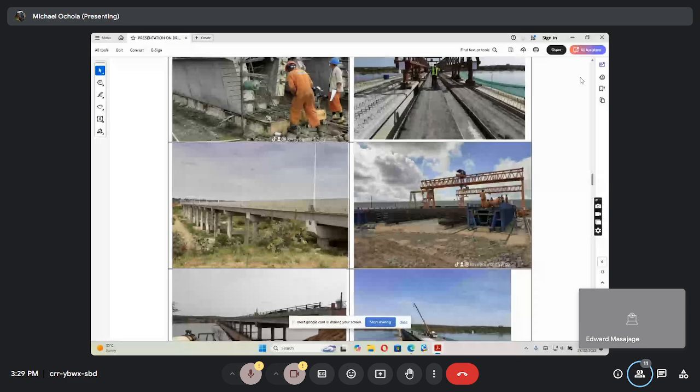We have where you have integral connection, where concrete is integrally connected or monolithically connected to the concrete. It takes both moment, shear, and tension. So you find this one, they have bearing. So elastomeric bearing is more continuous, but there is discontinuity, a disconnect between the deck and the pier support, the bearing. So they are sitting on bearing. So that, and they are safely supported.